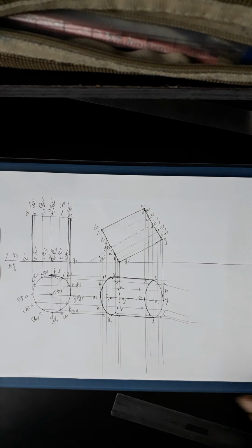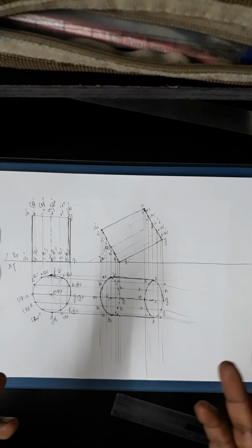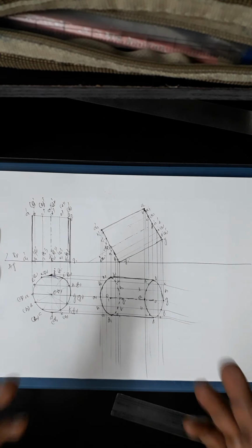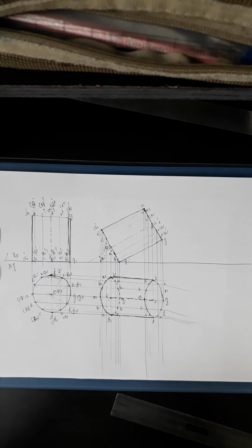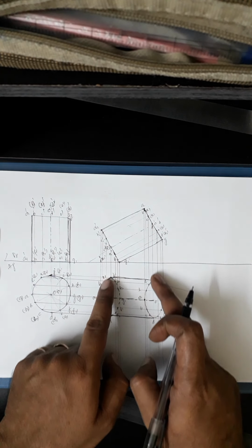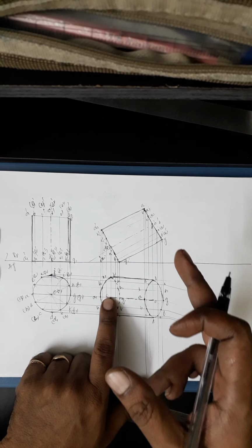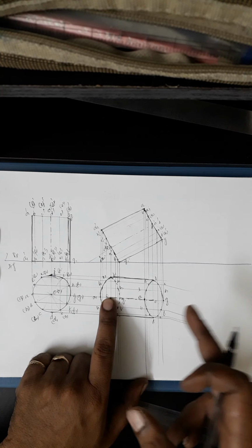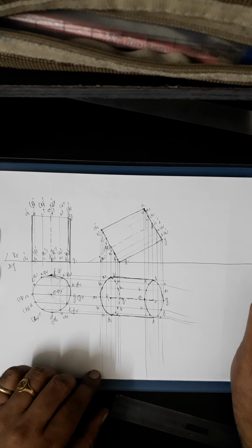Then he says the axis is inclined at 45 degrees to VP. If the axis is inclined 30 degrees to HP and 45 degrees to VP, without the three words, then you have to go for finding beta, because the projection of the axis on the top view becomes apparent. The given inclination will be the true inclination. Then you cannot use the true inclination for this apparent length when you redraw. So you have to find beta for this.